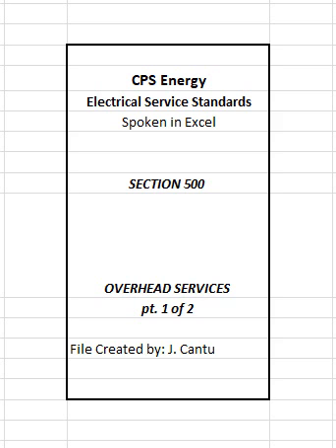505.2 Means of attachment. There are various types of hardware used to anchor the service drop conductors to the building or other structure depending on the type, size, and weight of the conductors. Typical anchoring options and related information are outlined in 1 through 4 below.